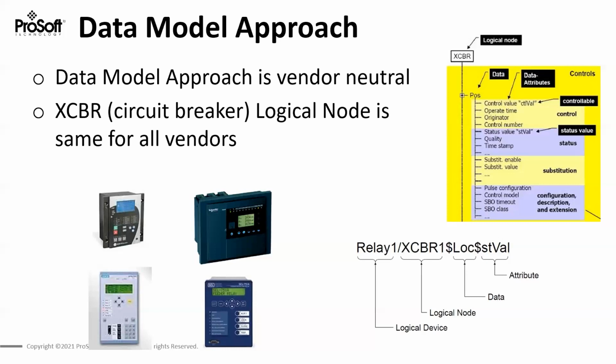And I look at this data model approach and these self-descriptive tags as really, if you think back to RSLogix 5 and 500 for PLC 5s and SLC 500s, and then out came ControlLogix and Studio 5000, or at the time RSLogix 5000. You now, instead of having N7 tags and N10 tags and F8, and hoping that somebody put comments in the PLC code, you really now have the ability to have these self-descriptive tags that mean something